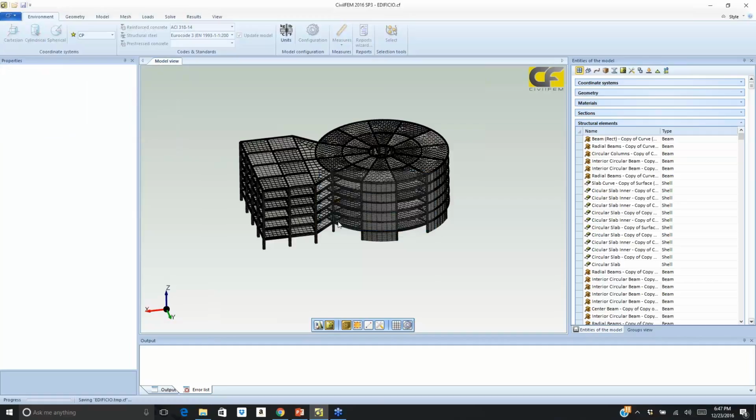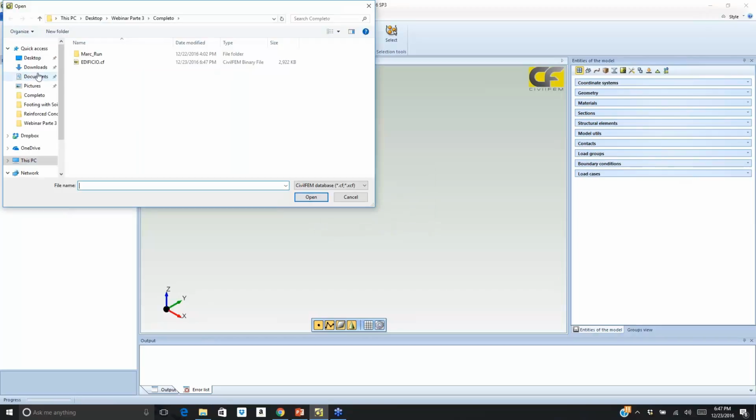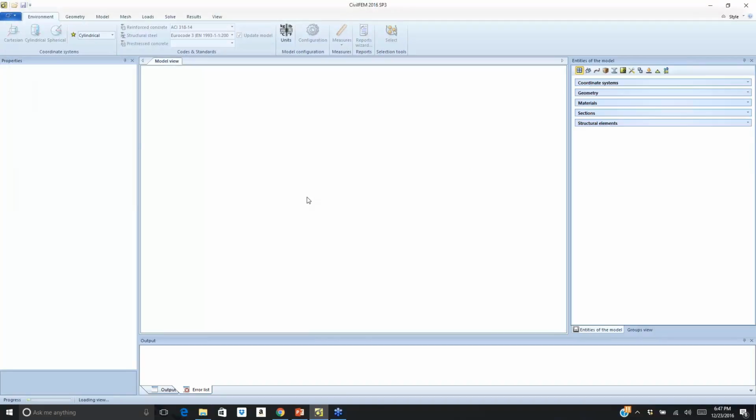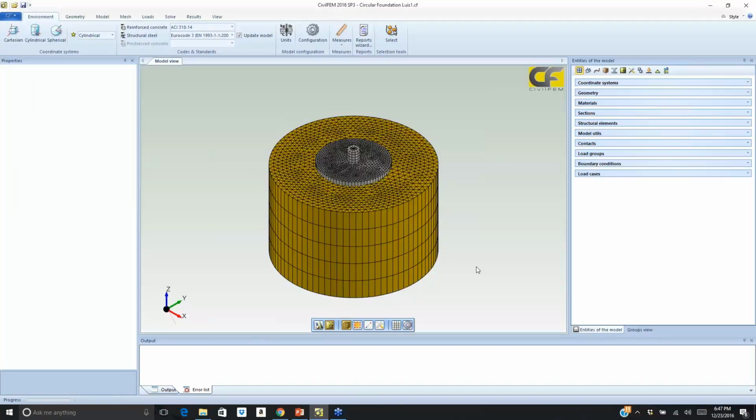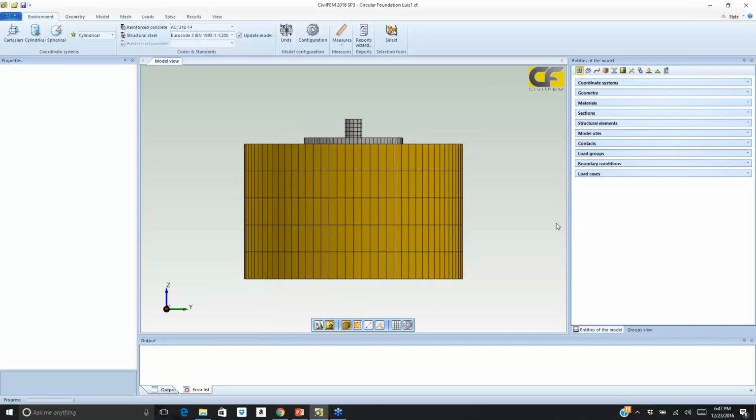This design is very exciting because it includes the soil, and we can assume that we have about 2,000 pounds per square foot capacity, and we will show that we don't exceed this capacity of the soil. Here we have three types of model. The amber represents the soil, and it's chosen to have a diameter about 3 times larger than the depth of the slab on ground. The small circle represents the isolated footer, and the center represents the column itself, a particular column.